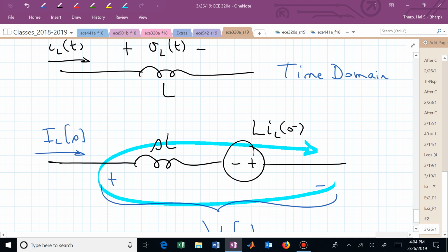It's an impulse, isn't it? A constant in the frequency domain, a 1, corresponds to an impulse. So here, the initial condition on that inductor is being created with an impulse waveform in the time domain. That's how we energize that inductor to establish its initial condition.